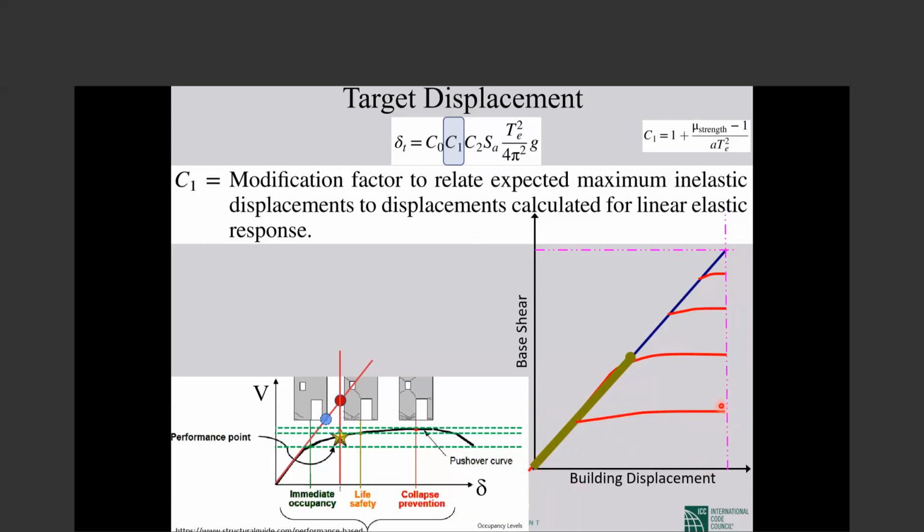But again, the maximum displacements are the same. We call that equal displacement. And from long ago, researchers have realized that for buildings with large period, this happens. So flexible buildings, taller buildings, buildings with larger period, they obey the equal displacement rule.